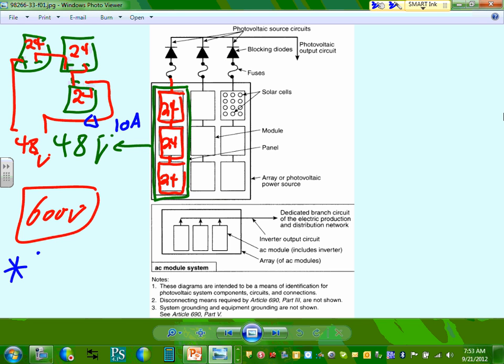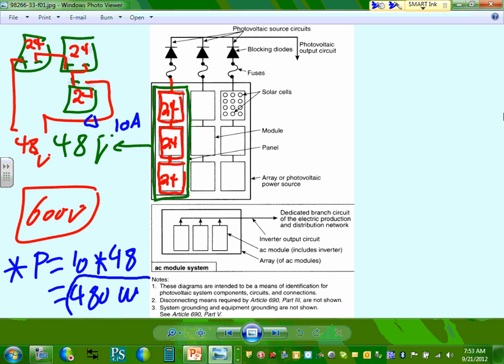Okay, anybody can tell me the power that's coming out of this system? I have 10 amps multiplied by what? 48. What do you get here? 480 watt. This is how much power you can get out of these 3 panels, modules, at 480 if they're generating 10 amps. Can I have thumbs up, Chad? This is basic math, guys. We did it with Mr. Ryman, series circuit.